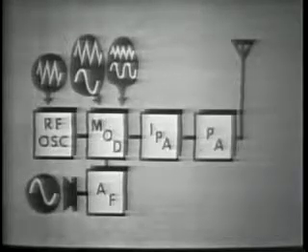When modulating 100%, each sideband voltage is only half as great as the carrier voltage. The audio frequency is not developed in the output because the RF resonant circuits have a very low impedance to audio.